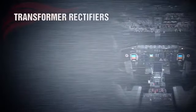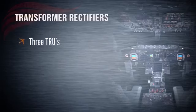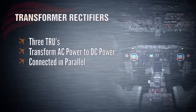We mentioned the TRUs before, so let's explain them now. The 737NG has 3 of these components, which essentially transform and rectify the 115-volt AC power to unregulated 28-volt DC power for the DC buses. The 3 transformer rectifiers are connected in parallel, which means if one of them fails, the other 2 may give backup. The TRUs are connected according to the following logic.